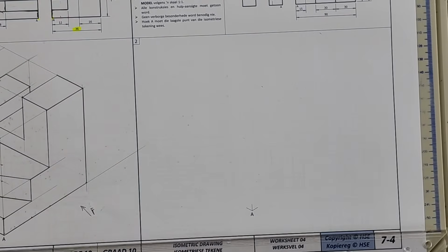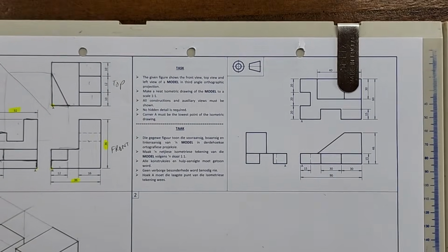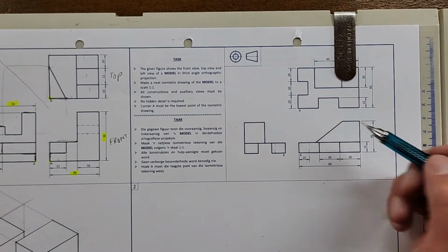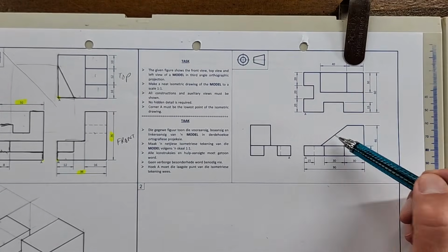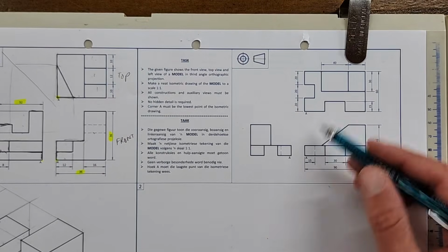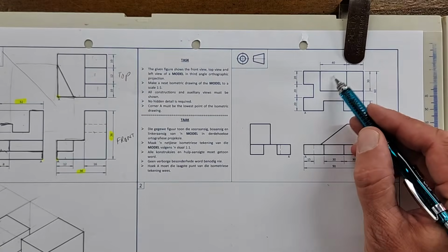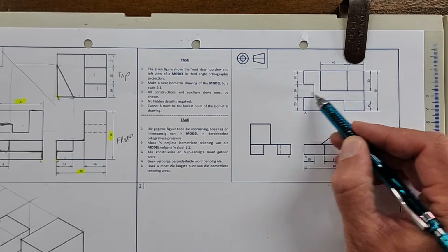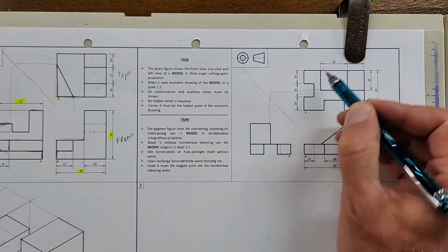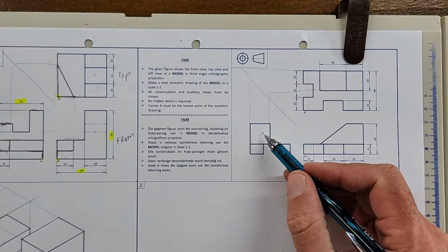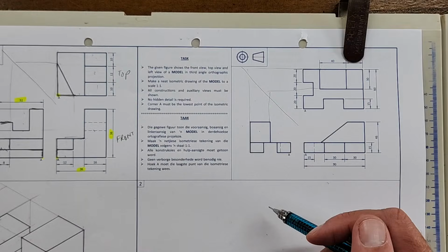We're going to quickly go over to the right-hand side. Doing the same exercise now, looking at what is given. We've got top view, front view, left view. If we just look at the front view, we've got an angle there with a flat surface, which is this surface here in the top view. If I bring that across, if I did put my 45 here, I would see that that lines up with that. That there at the back lines up with that. Okay? And then, again, here's another mistake in this drawing.